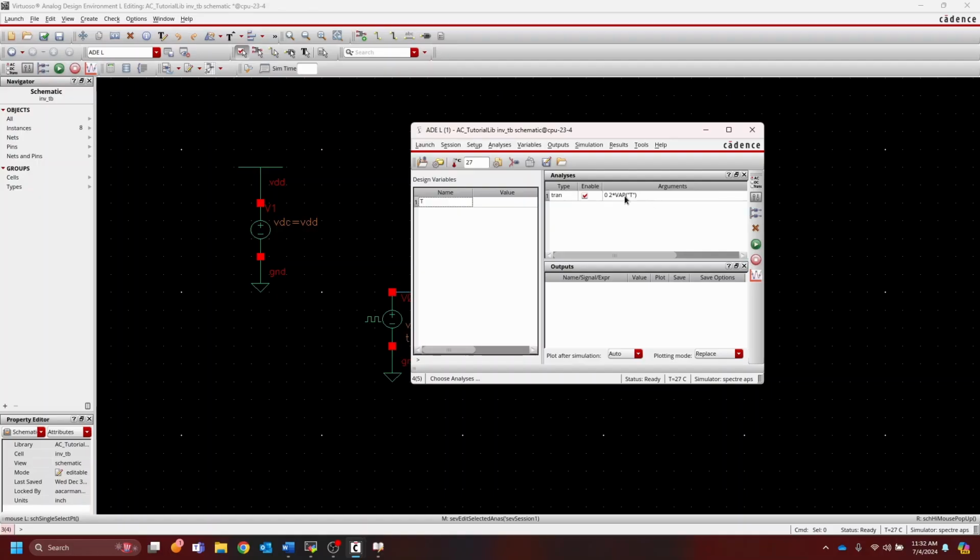So now we have our transient here. We can see it already added a T here because we defined it up here. But if we copy the rest of our variables, we can now define our rise time. Let's set it 100 pico. VDD, we'll keep it 1 volt. VNDC, we don't want any DC value. We want to keep it as 0 for this simulation. And then for our T, let's do something like 1 nano for now, 1 nanosecond.